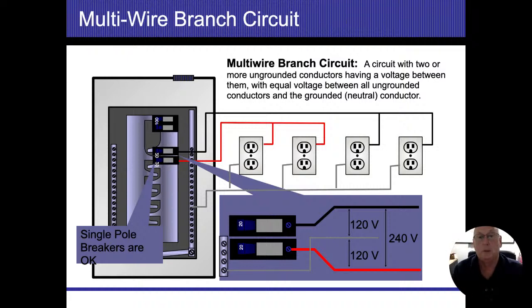As long as the amperage is the same or whatever it is, the neutrals are going to only carry the balance, if anything, back to the neutral bus bar. I do not have to have a 240 circuit or a 240 breaker in this situation.